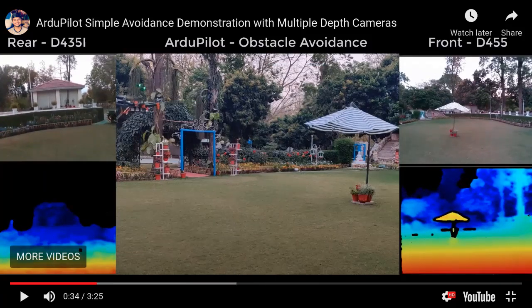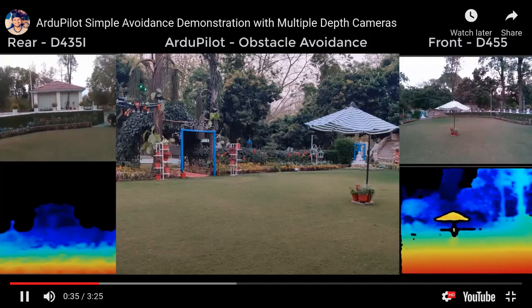The frames per second that I was getting out of the two cameras was a little below 10, because the Jetson Nano can't really keep up, it's not good with multi-camera support. If you had just one camera, you'd get 15, 16 frames per second, which is sufficient. But with two cameras, it was lagging. I think if I upgrade to a better, more expensive Jetson computer, like the TX2 perhaps, it's going to be slightly better. But for a demonstration, this works.